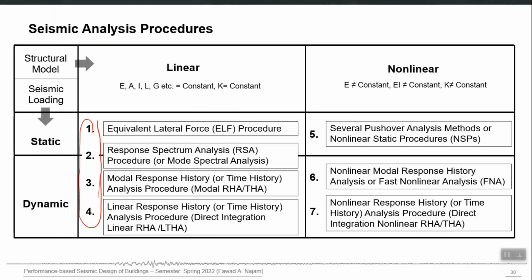The more a structure is ductile, the more we can rely on its ductility and useful properties, which means the higher R we can use for that particular case. We can design that on further reduced forces. For very ductile types of structures, this R can be as high as 8, right.